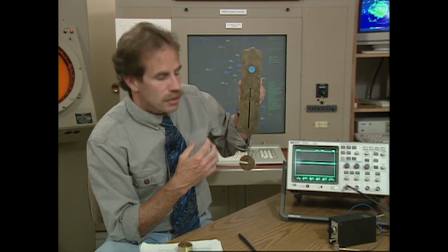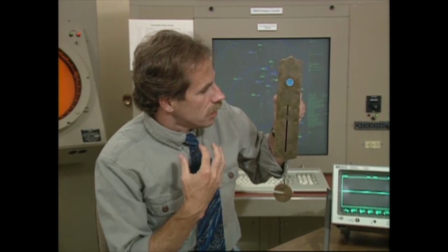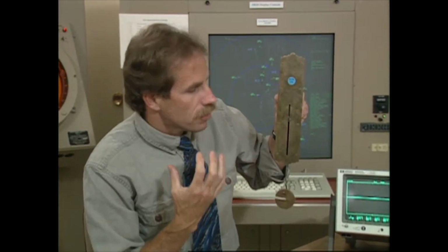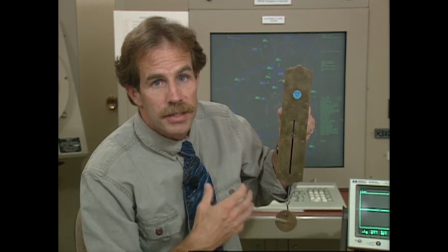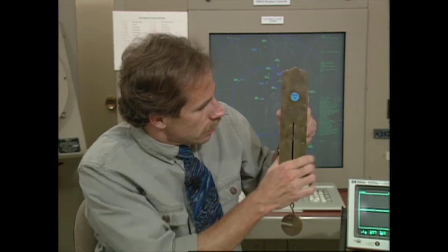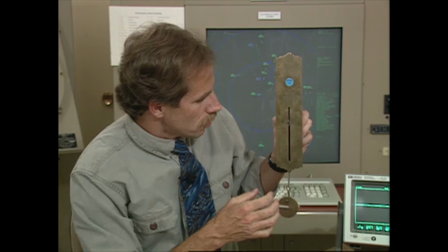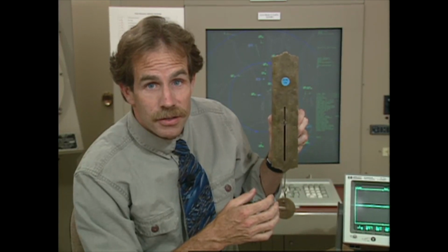Because on the surface of the Earth, even though this isn't moving, it feels that 1g acceleration down. The acceleration we feel on the Earth is a combination of the gravitational acceleration and something that we call the inertial acceleration. And in fact, that inertial acceleration is what you would integrate to get velocity. Now, like I say, most accelerometers use this principle. However, most accelerometers aren't this crude.